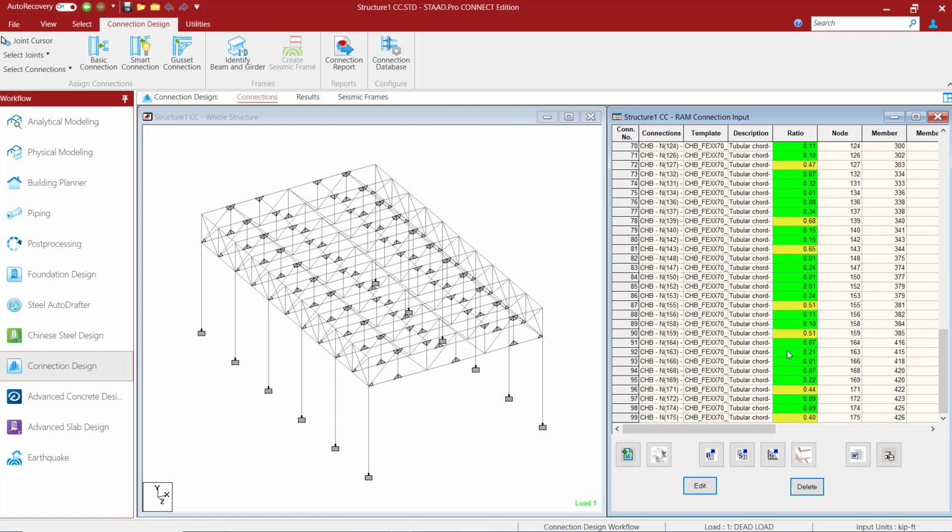Everything worked out fine. We found a connection that was code compliant that did not produce any warnings. Any field that is yellow means that we did find a connection that passed all code checks, but we're going to produce a warning because something in the code that is recommended you did not follow. Okay, so we have yellow and green over here.